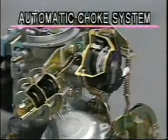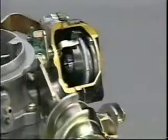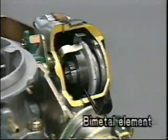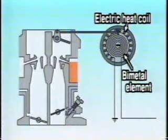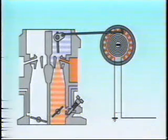At present, as is shown here, the most common type is the automatic choke system. We will also introduce the electric automatic choke, which is currently in use in most vehicles. The automatic choke is controlled by the contraction and expansion of a bimetal element. When the temperature falls below a set level, depressing and releasing the accelerator pedal will cause the choke to be completely closed by the contraction of the bimetal element. After the engine is started, current will flow through the electronic coil. This will generate heat, which will cause the bimetal element to expand and open the choke either slightly or all the way.